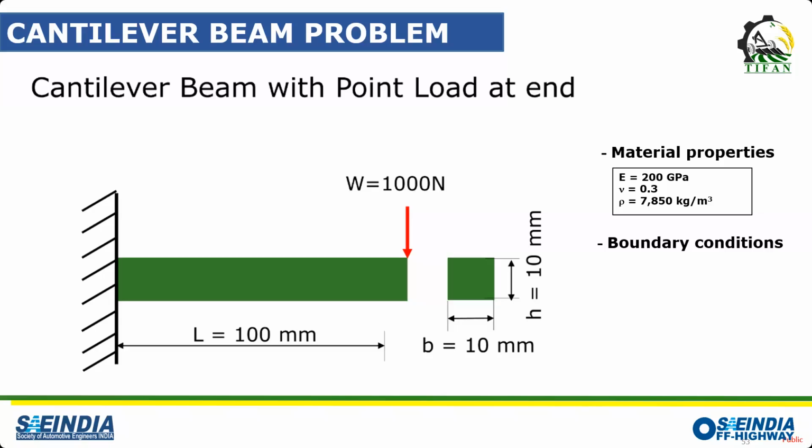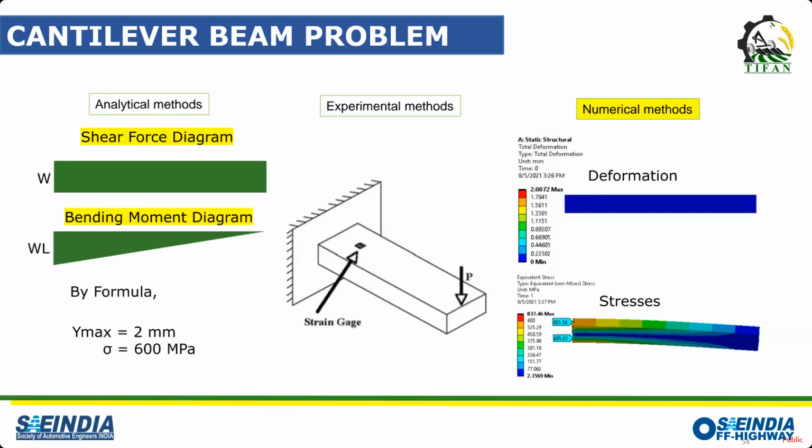We can go to the next slide, Dharmendra. If you wish, you can draw the shear force diagram and bending moment diagram for it. For the shear force diagram, we can just draw the FBD of this. It will be a straight line, one side P, and the reaction force from the bottom will be P. To calculate the shear force, take any cross section; the algebraic sum of forces either to the right or to the left of the section should equal the shear force at that point.